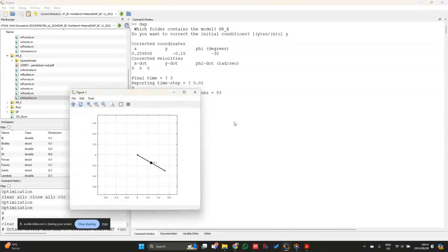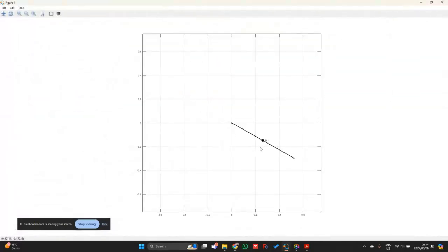And if I click any button over here, we can see here at the start, it's actually a bit difficult to see, but it's still in the process of accelerating over here. So let's see if I maybe make this larger. So you can see it's starting to move, but it's moving fairly slow. Yeah, so it might not have been the best choice to use 0.01 seconds. I think then it's going to run for quite a while. But we can see now that this thing is starting to move. I just want to see how long it takes for this thing to actually reach a reasonable velocity.